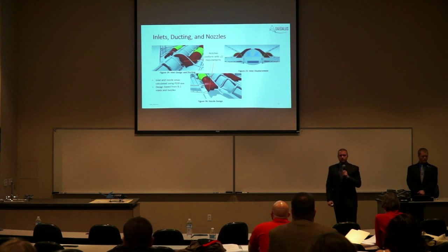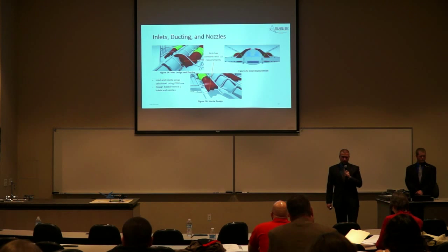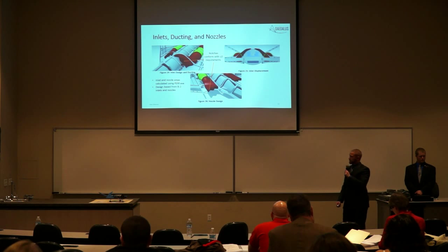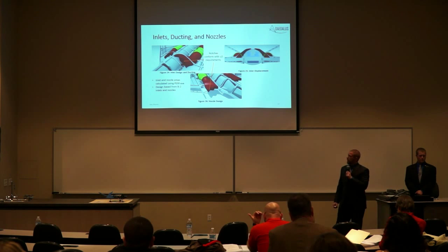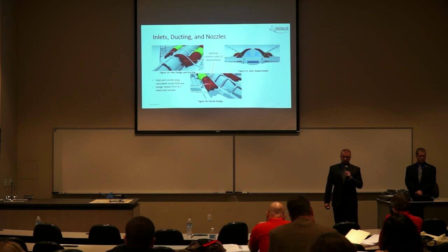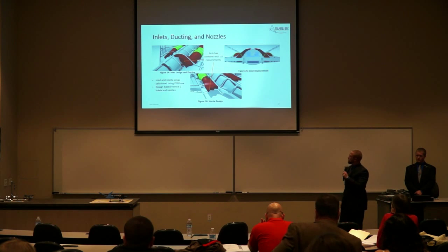As a result of our engines being embedded in the wing, we require a system of ducting that connects our inlets and nozzles. This is similarly designed to the B2, however, due to the wing of the YB-3 being thinner than that of the B2, our inlet was shifted towards the fuselage. Each of the inlet areas as well as nozzle areas were calculated using software called perf.exe.